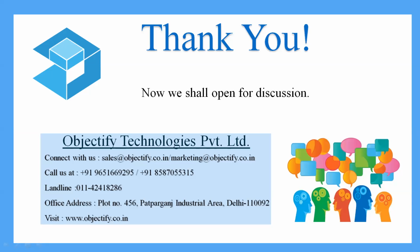So first of all, support structures are needed in very few specific technologies. Not all technologies demand it. Mostly the powder bed fusion of a nylon type of polymer, you don't need support in that. It is self-supporting and you can print it without support considerations. But in case of stereolithography, fused deposition modeling, and in case of metal, the support generation becomes very key. The reason behind it is the geometry will collapse if there are no supports provided.